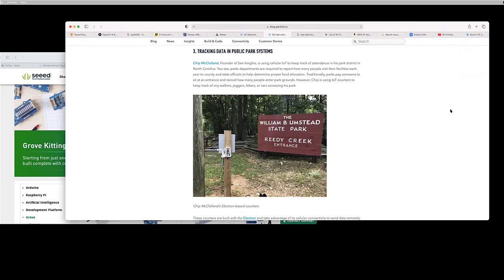Photo eyes require power. They're not going to be a low power device. They're going to require a pretty chunky battery or an outlet to plug into to power these devices. And so a lot of these lines already have existing photo eyes on them that are powered by a power supply back in a box somewhere. And so if there's a way that you could piggyback on the line coming in, you could get a counter.